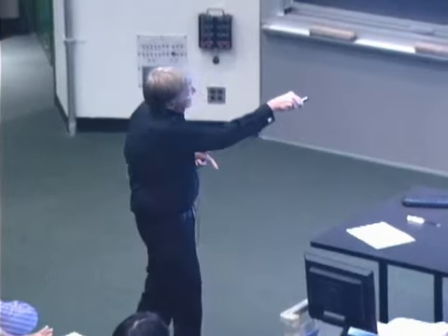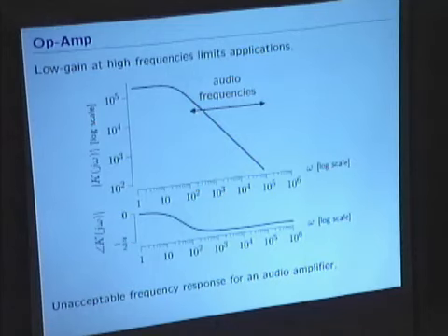Unfortunately, the range where it's not very good is most of the range. So if you thought about an op-amp doing even a very low frequency problem like audio signal processing, most of the frequencies that are of interest to audio are in the region where the op-amp's not working too well. We hear sounds from about 20 hertz to about 20 kilohertz, and that range is indicated by the red arrow, and you can see that's not where the op-amp is working ideally.